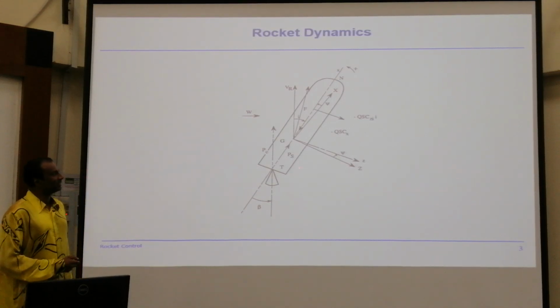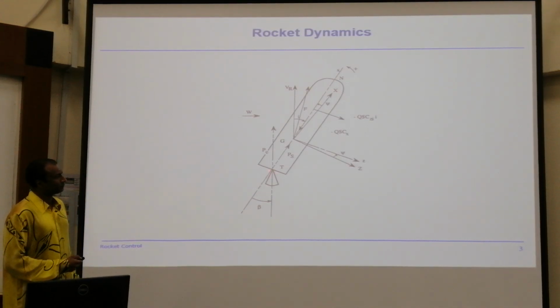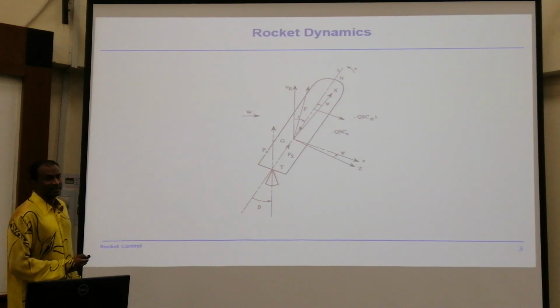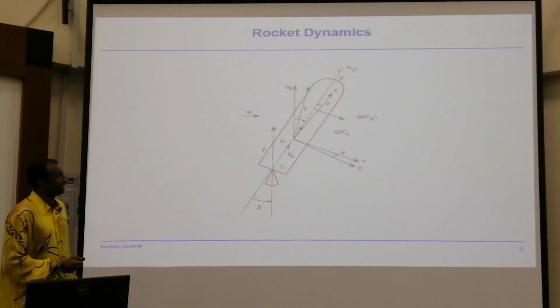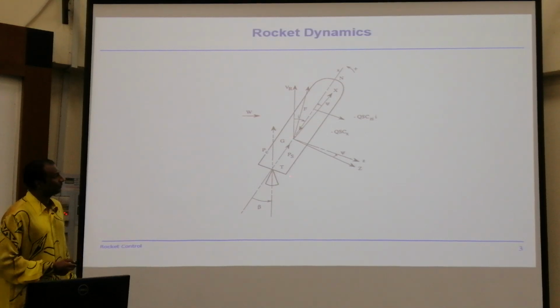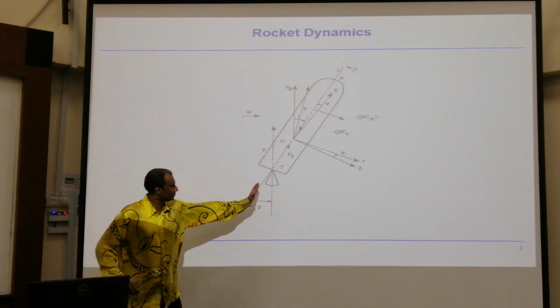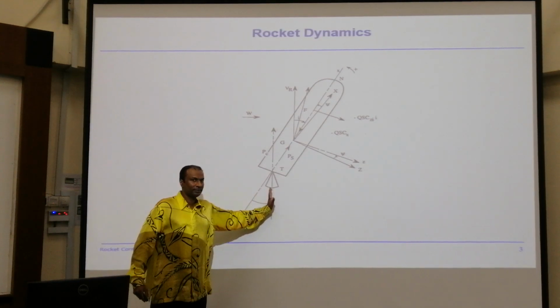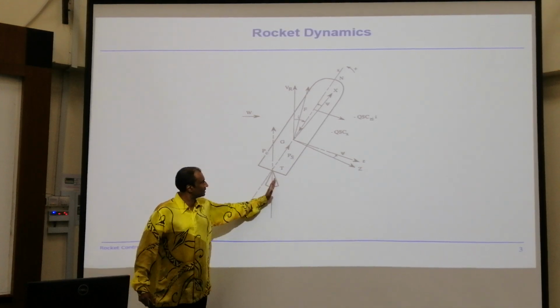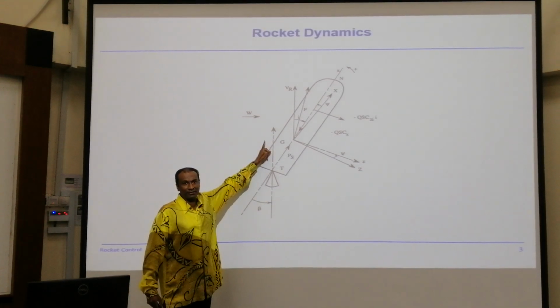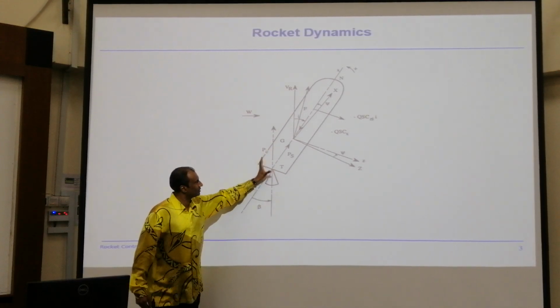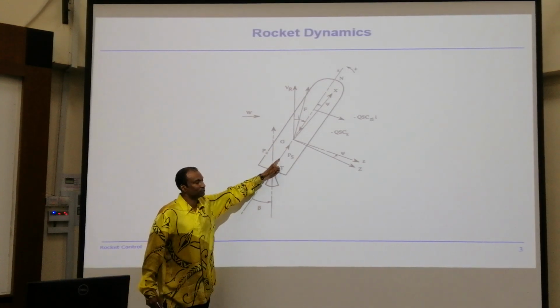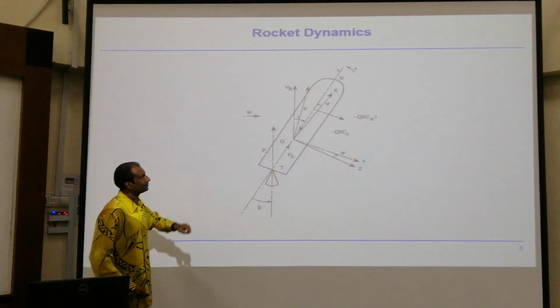So what I'm saying is that the relative difference between the articulation and the CG will be slightly closer. Yeah, this is just exaggerated so that I can draw as I want. So this is uncontrolled thrust actually you have. This is a controlled thrust because when I move the beta angle, thrust comes up. This is where the actual thrust is going to hit me, right? That's how it will go. And while you're already flying here, it's practically going to be your controlled thrust. Alright?